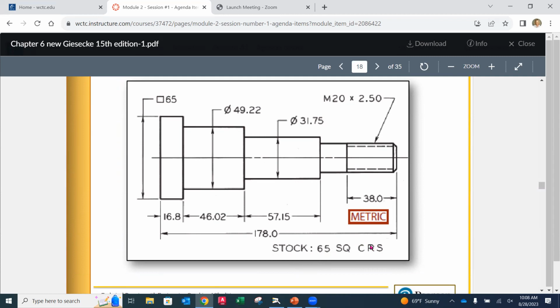Always at least two views. It brings clarity, because as we look at this, do you see how somebody can glance at this? This is a center line going through here. Center lines most often show lines of symmetry, but people go right to thinking these are circular features. So when I look at this end part, this collar, it's got the square in front of it, but do you see how somebody could jump to this and think, oh, that's circular, with a glance? But if there were a side view showing the square on that side, now it's clear.